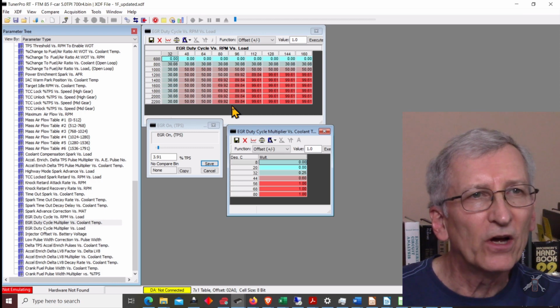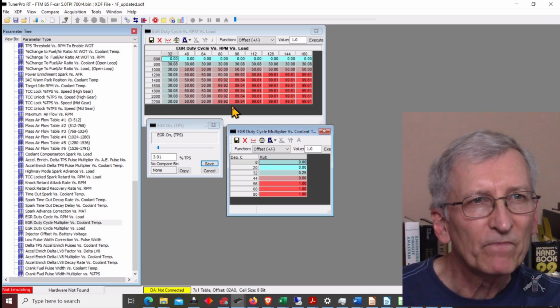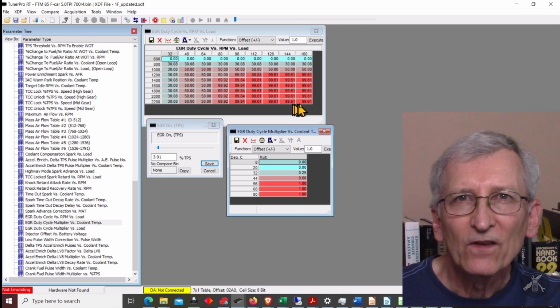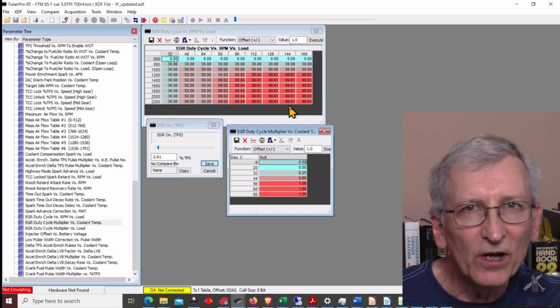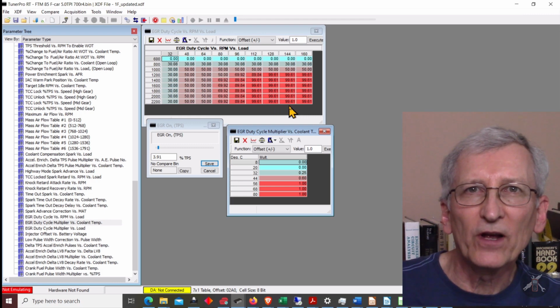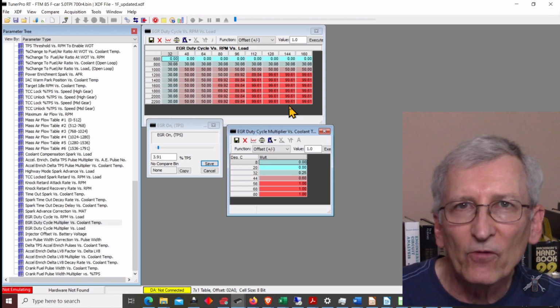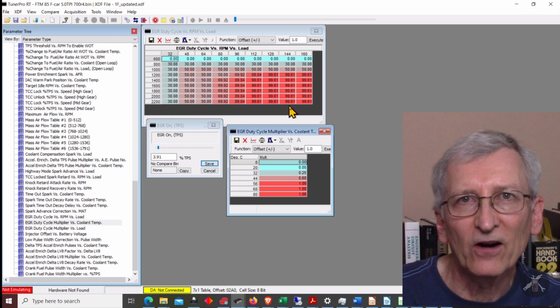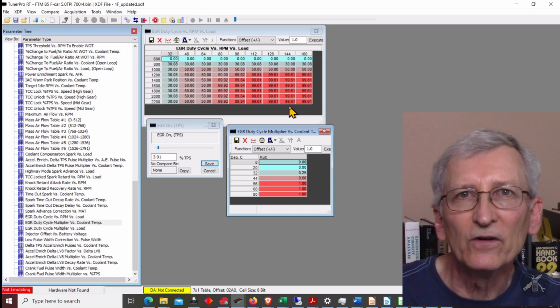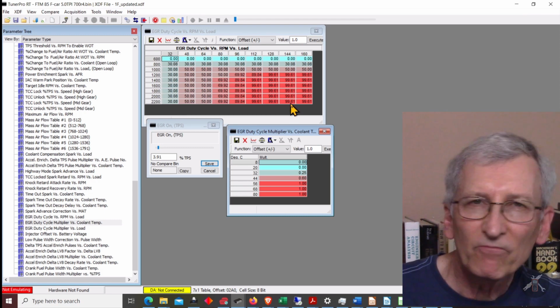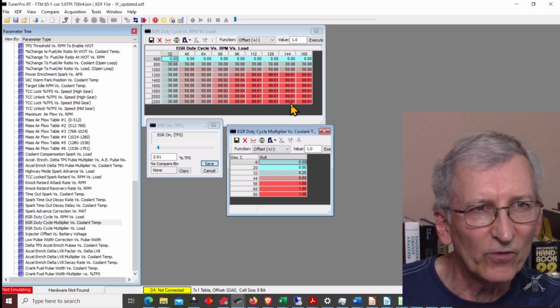you can say I want it to be 100% and wide open out here, but the reality is that this valve is driven off of vacuum. And when you get to heavy throttle, there's no vacuum left. Your vacuum drops, your manifold absolute pressure comes up, and your vacuum goes down. And this valve will naturally close as you get hard on the throttle. New cars have electronically driven EGR valves, and they can be open at wide open throttle. But generally these vacuum driven ones can't.